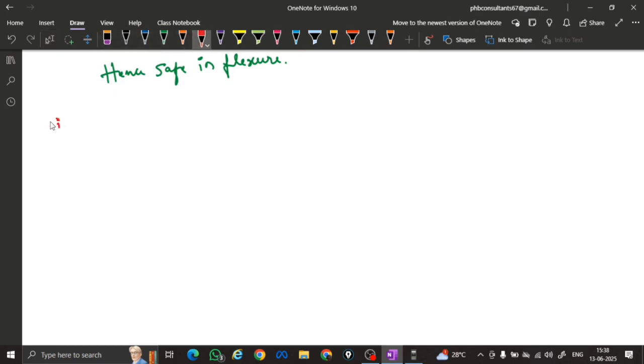In shear, first we will calculate the one-way. You can check two-way shear also first. After the two-way shear check, one-way shear will almost all the time pass. But still I will calculate one-way shear first only.